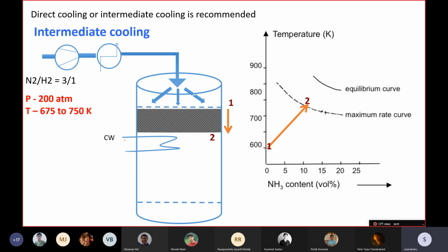There is a heating coil placed between the beds, and through that coil cold water is circulated, so that the whole area inside the reactor is filled with cooling water circulation and coils, so that every portion of the reactant can get cooled down. External cooling water circulation will not be possible for packed bed reactors.